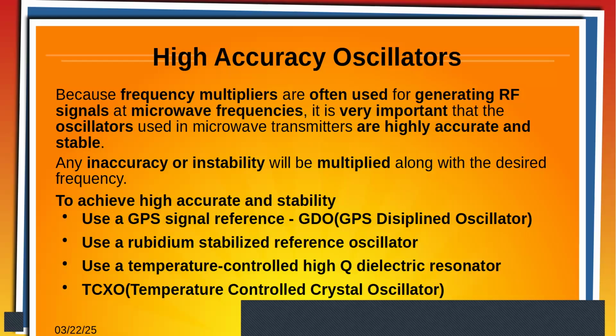It's crazy. Whatever the cesium clock is. And then, of course, you can have your own rubidium stabilized reference oscillator in the laboratory, maybe. Or you can use a temperature controlled high dielectric resonator, which is one of those ceramic ones that Chuck was talking about, or a TCXO, a temperature controlled crystal oscillator.